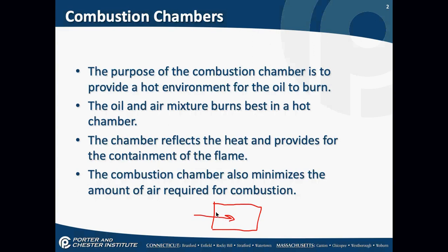If I isolate an area inside this drum with a porous material, in other words, not a solid wall, but a porous material where flame and air can be somewhat contained, and then maybe have a smaller passage for the products of combustion, I have a much tighter control on my combustion process.